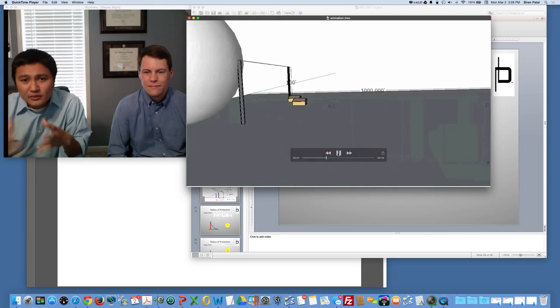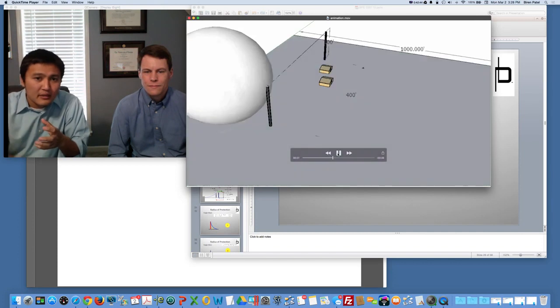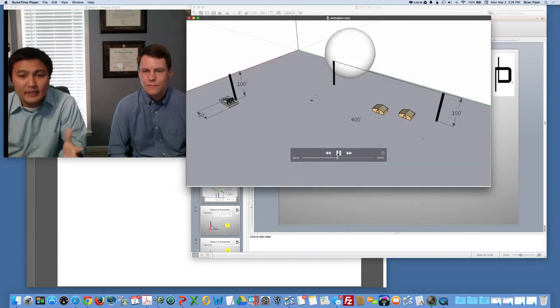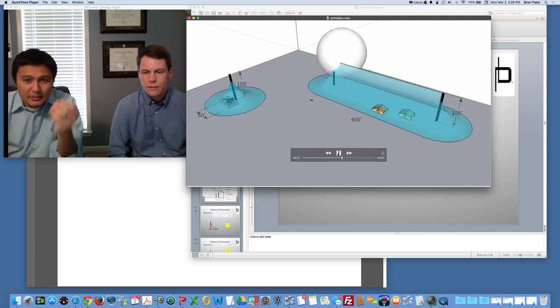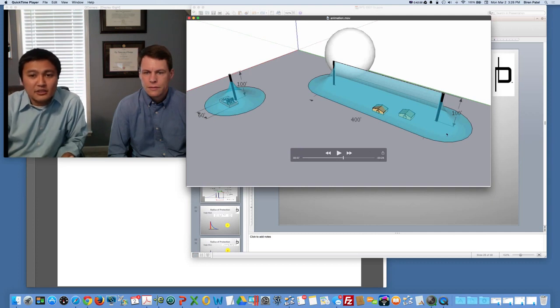We're going to roll the sphere, and every time we hit a shielding electrode, whether we hit a mast or a wire, we're going to stop the sphere and go around it. And it's going to create some zones of protection. You can kind of picture the zones of protection already, but here we go. In 3D, I like to call this a tent shape. You've created this tent shape zone of protection. The sphere could not get through the wire.